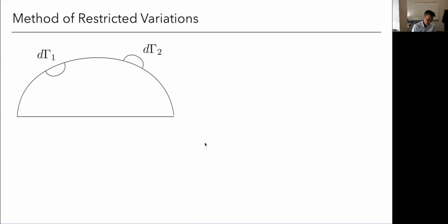Imagine that I have a lift distribution, and it could be any shape, which is arbitrary, right? And I want to modify it, perturb it, make infinitesimal variations until I can get towards an optimal, the minimum drag solution. So for example, in this little cartoon here, let's say I took out some small chunk of circulation at some point and maybe added it or changed another part somewhere else, right? So I'm just going to make these small perturbations, arbitrary locations on the wing of arbitrary amounts.